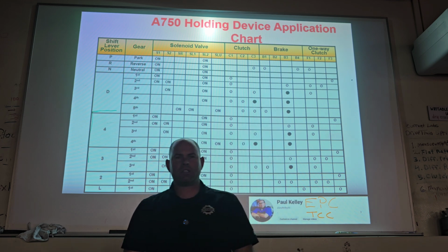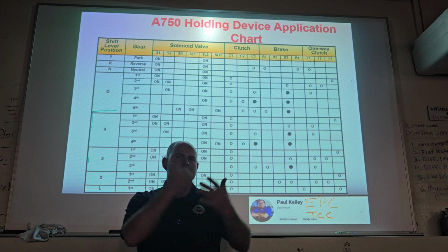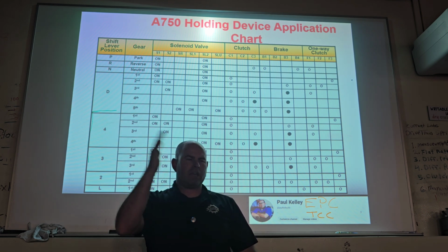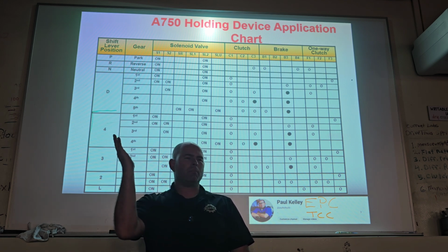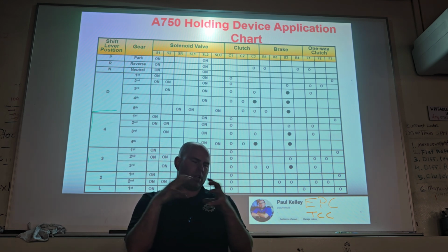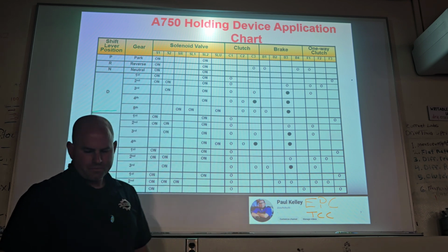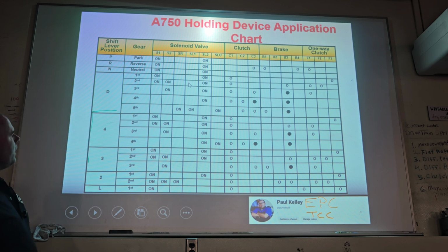A shift solenoid is going to be like, oh, you want second? How about no? First, first, first, right? It's not even initiating the shift. Now, if it tries to go to second, and second's like zing, and then it goes to third, it was like, what the heck was that? Second gear was just a neutral mess. You think that probably a clutch is slipping. See kind of how it's different? It's just different. Cool?